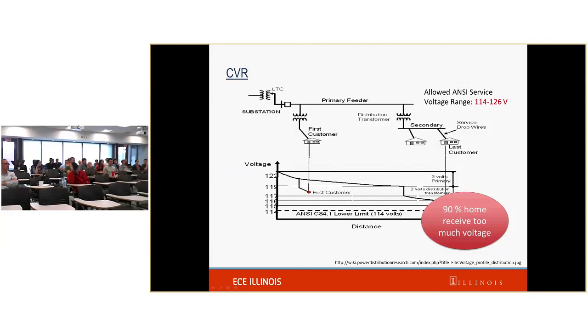Right now the constraint for lowering the tap is the voltage for the last house, because conventionally the voltage should decrease monotonically, right? So if you can somehow use reactive power support to flatten out the entire feeder voltage profile, then you can do the maximum drop, and then you can see more benefit of CVR.